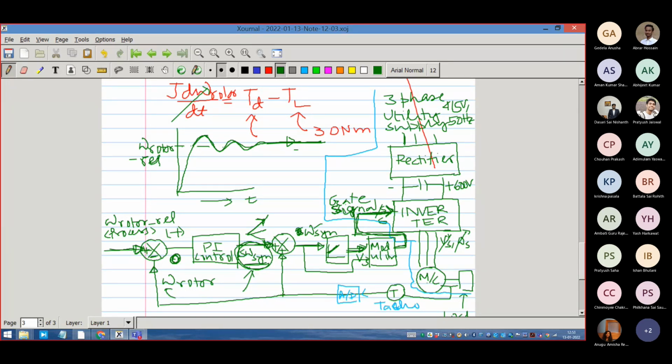The fundamental level is that it is supposed to maintain the speed, and the error in the speed will result in the correction. This is the error, and it is resulting in correction in the correct direction. If the error is positive, I must increase the slip speed. Error positive means that more torque is required than what it is at that moment. So it will increase that. So this is the way this system will work. Understood it? Okay. Understood the control system?